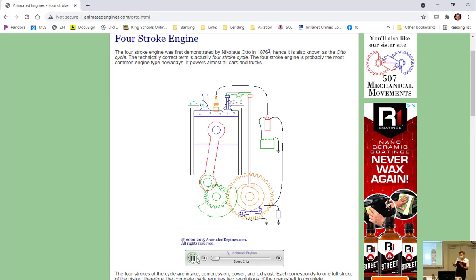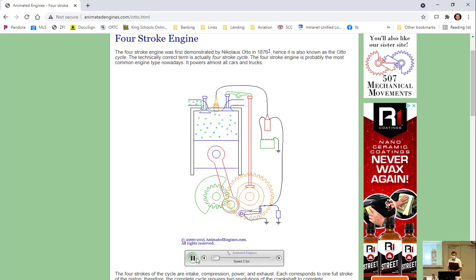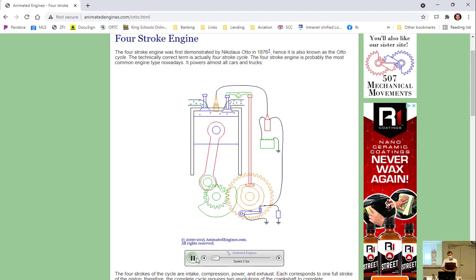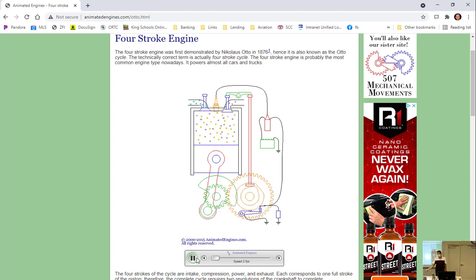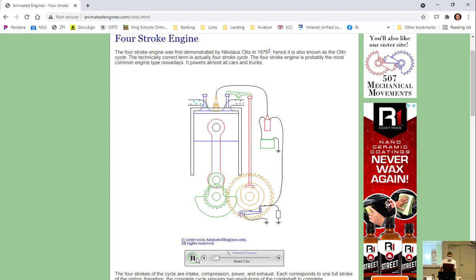Now, in old-timey automobiles, I guess actually all automobiles, they rely upon the battery to create an ignition source. We'll talk about the old-style Kettering ignition system, which this one is represented because it's got a battery, it's got a coil, it's got points, capacitor, a lot of the things you're going to recognize. So what that does is it creates the spark here, but you need a battery. Don't want that in an aircraft.